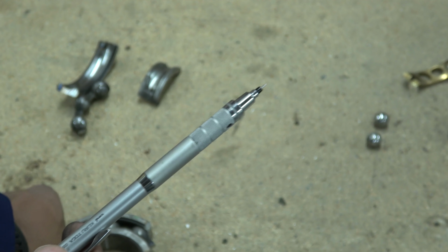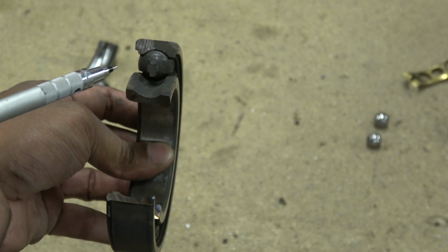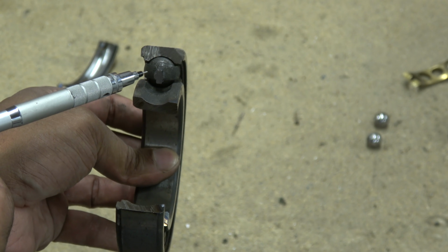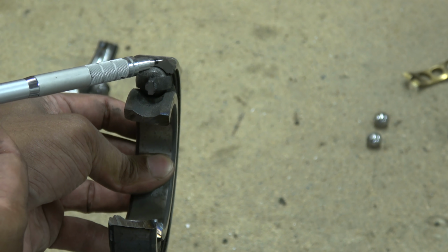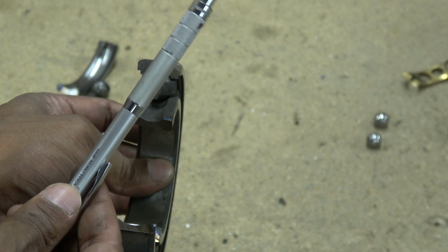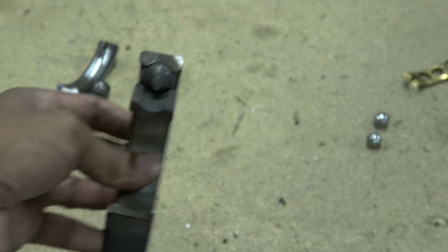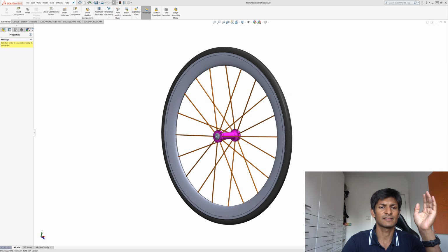If you do the same thing with the deep groove ball bearing, the contact angle is much, much shallower, so it's contacting here and here, but it will take load in both directions, so its contact angle looks a lot more like that in terms of the pencil mark. So I've done a few slides and things so you get your head around this.